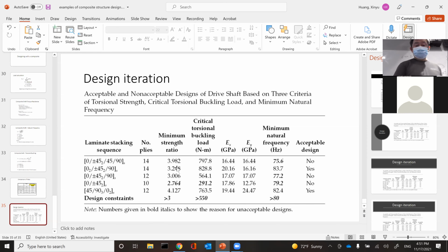And then you have a much higher critical buckling load, and you have decent natural frequencies. That could be an option for going further. There are other issues like the joint design, the fastening scheme at the ends. That's also important, but this addresses the bulk of the shaft.